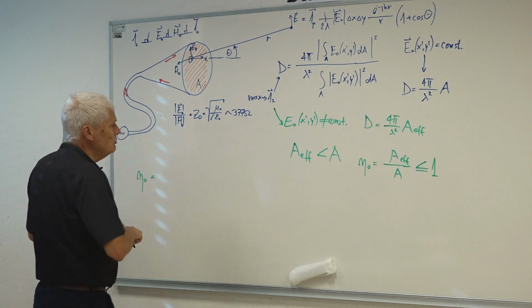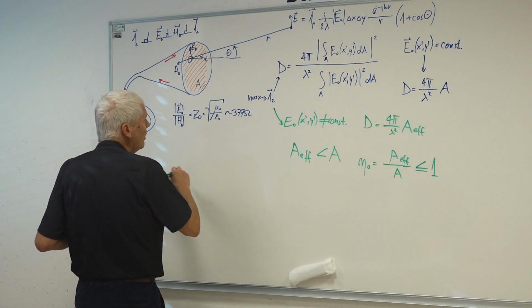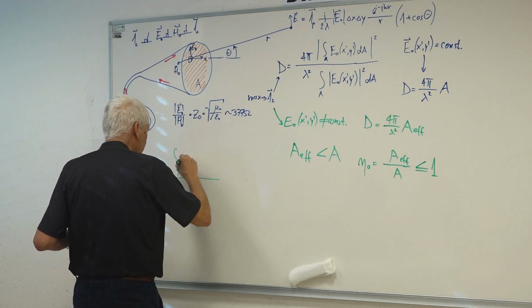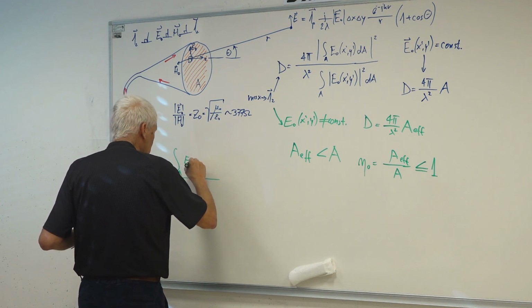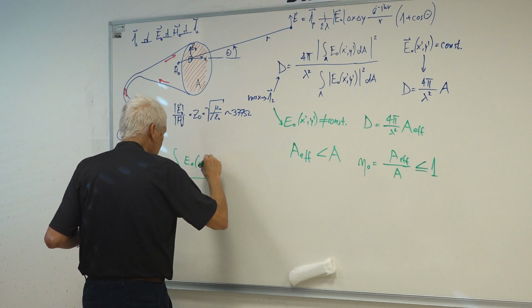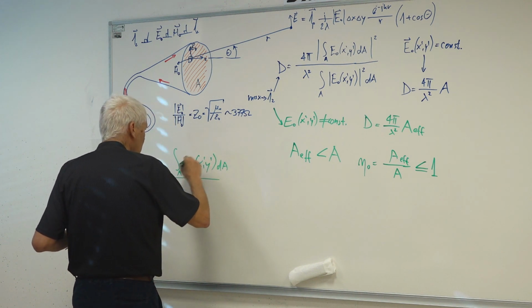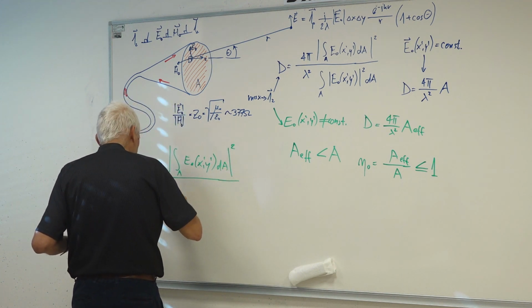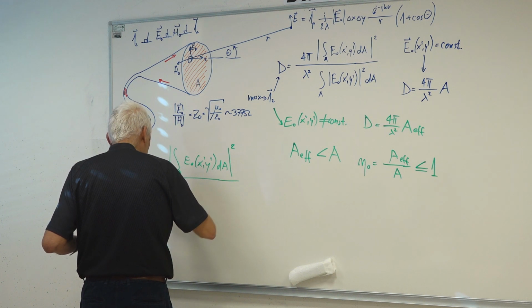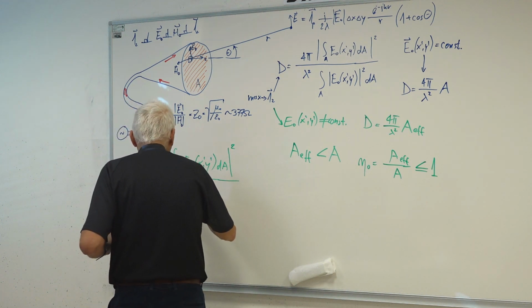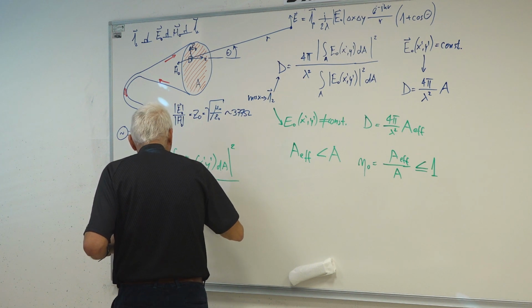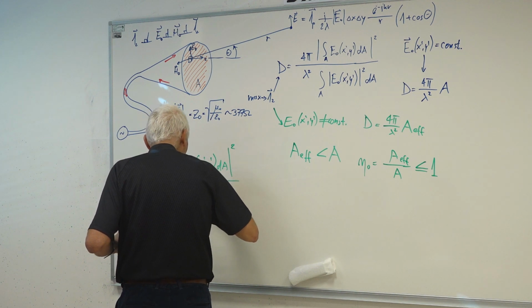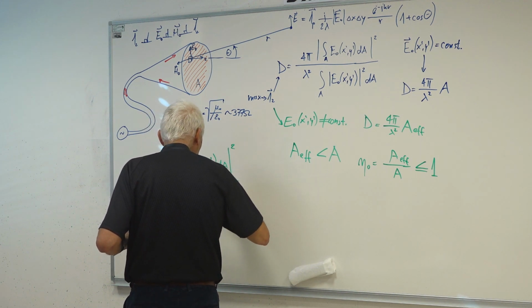So this aperture efficiency can be calculated with our integrals. How? This way. We have the integral over the aperture of the field, E y prime dA, take the absolute value squared, and below we have A times, I prefer not to write dots when we don't have vectors, the integral over A, and here is the power flowing through the aperture, field squared dA.